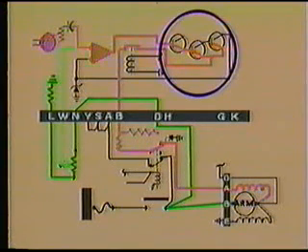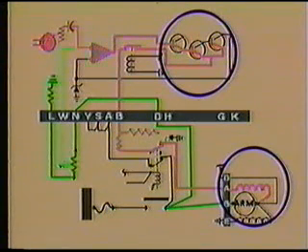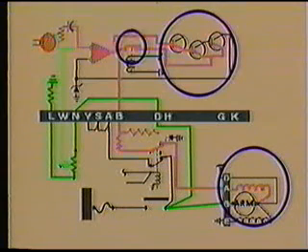From the operational amplifier, the output travels to several transistors. These components serve only to amplify the output of the operational amplifier to a point that it can be supplied to the field of the generator, which we learned controls the generator's output. Note that before the signal reaches the generator, it must pass through the closed contacts of the reset portion of the trip relay and the generator output relay.